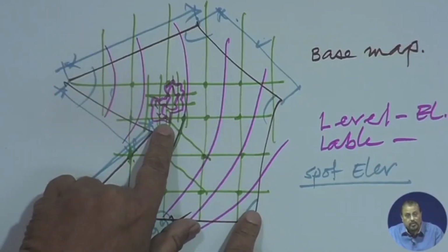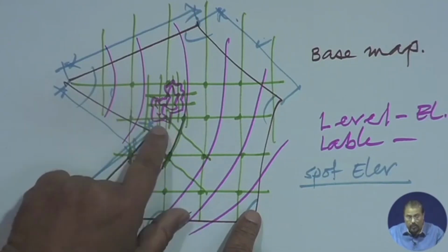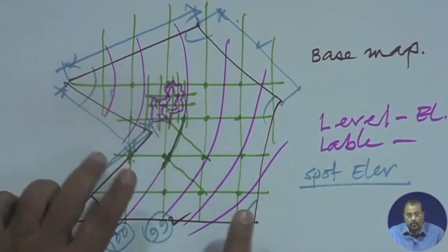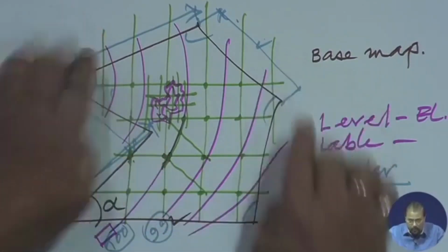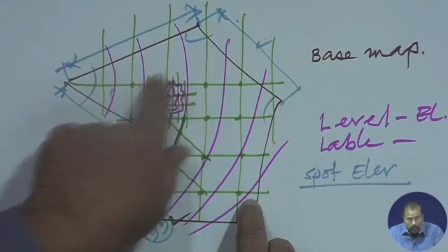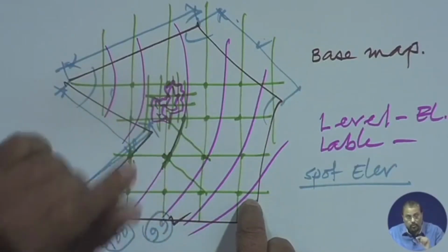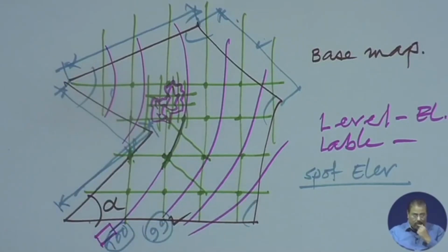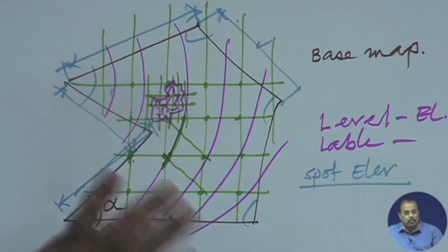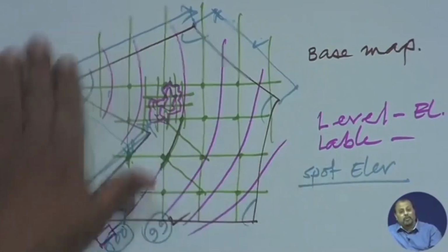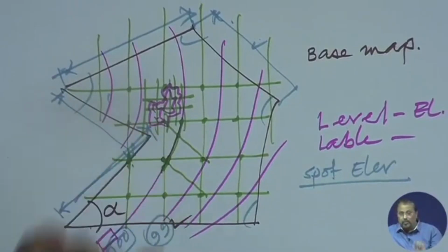But suddenly I found that there is something like this, and there may be a rock outcrop, and I would take note of it. Not only will I take note of it, I will also record it in my drawing. So I will ask him that, okay, this is one grid, it is the next grid, which I can always use, but give me the detail of this in terms of its height, topography, contours and everything. Maybe at the site, before the survey has been done, I can also decide that this particular element, which is a rock outcrop, I will use in my landscape. I will not destroy it, I will not flatten it just because the entire site is flat. I will use this for very specific reasons.